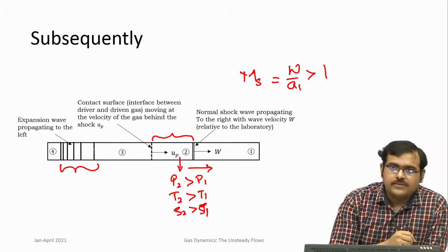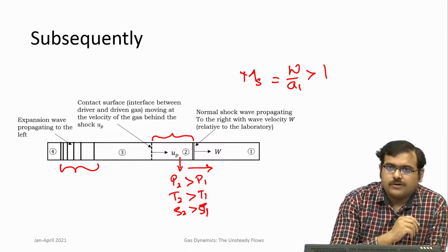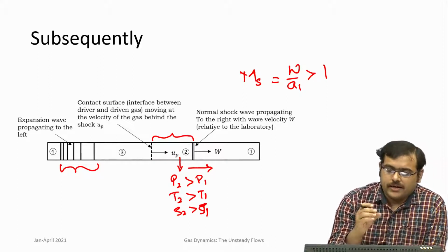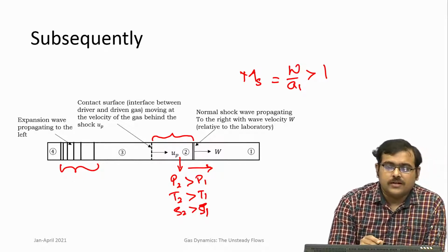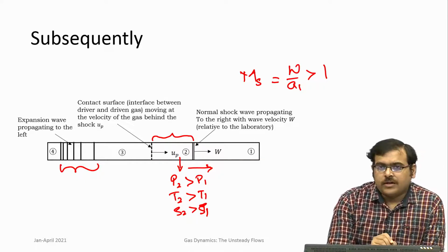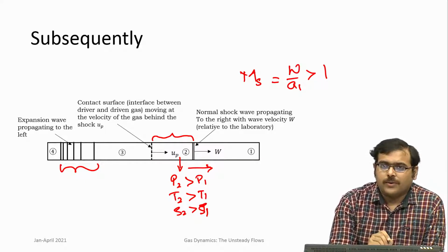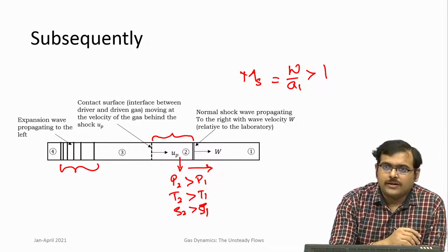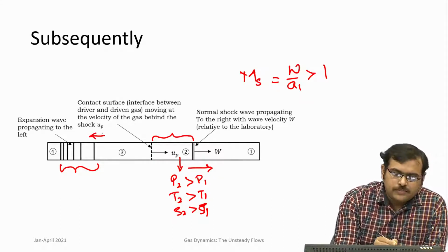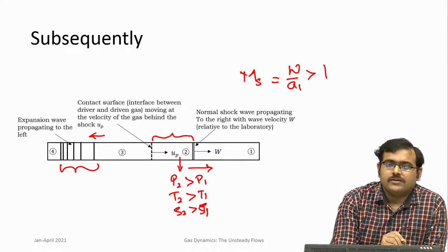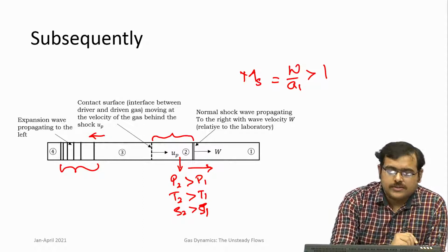Okay. So, these are expansion waves that are shown as a series of waves, and that is true for expansion waves because they are not a sharp discontinuity like a shock. And this is something that we have discussed earlier on, that there is no expansion shock, it violates the second law of thermodynamics. So, expansion processes are more gradual and they are isentropic. So, it is true here also, these are expansion waves and they travel left into the driver section. So, there they reduce the pressure.